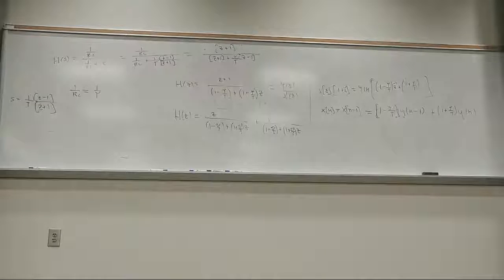You want that when you're sampling the signal, that signal undergoes the same filter properties, low frequency filtering. So now you can take the filter that you're familiar with, do the transforms, which I did only in the z domain, and now I have a difference equation that's easy to implement. All right, sample and hold, store, and now you've got a discrete time filter that does the exact same thing as a continuous time filter.